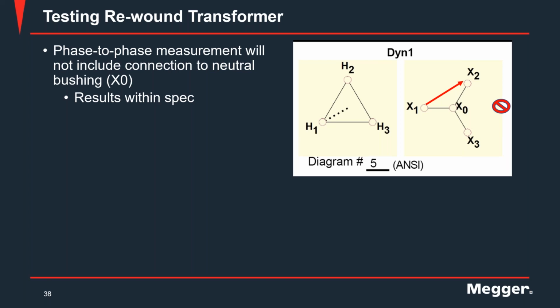So that's why I made it a point to discuss that IEEE note and the fact that there is information in the standards that will allow you to accommodate these situations. That's why it becomes important to have a reference measurement, let's say from the factory or from the last time the transformer was tested. That allows you to understand the specifics of how winding resistance has changed, whether there has been a large deviation. And if there hasn't been, sometimes it could be the inherent behavior of the resistance as is.